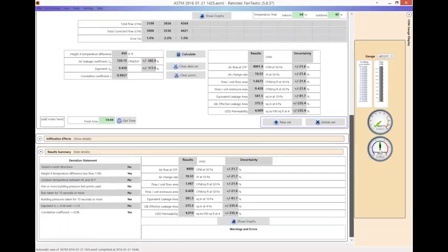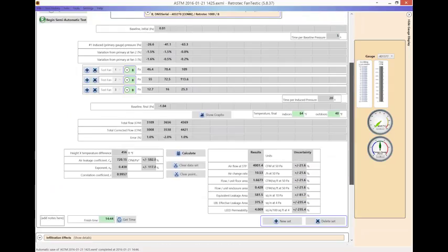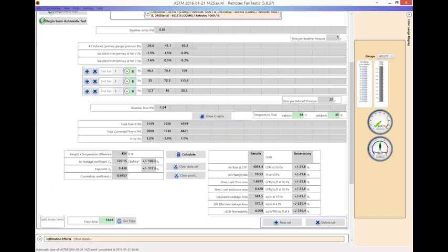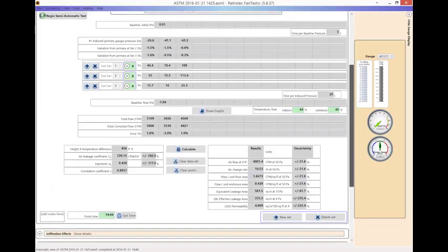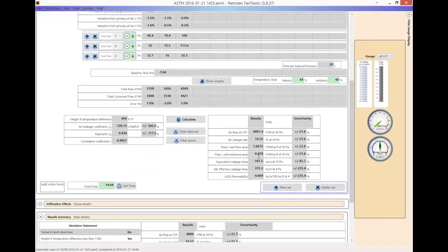So let's scroll back up, and I can show you that over here my results are based upon the information we put in the building. Remember our square footage and enclosure. I can see my air change rate is 10.53. So definitely not a well sealed structure that we have here. And you may be looking for flow per enclosure at CFM per square foot. 0.4 is kind of the higher range of that. And this is, again, leakage per surface area of the structure. And just above that, I have my air change rate of 10.53.